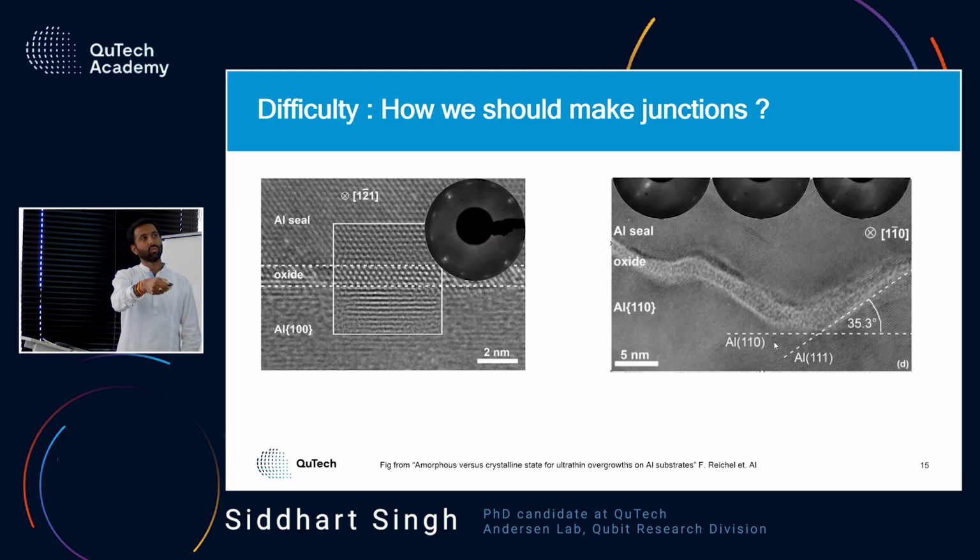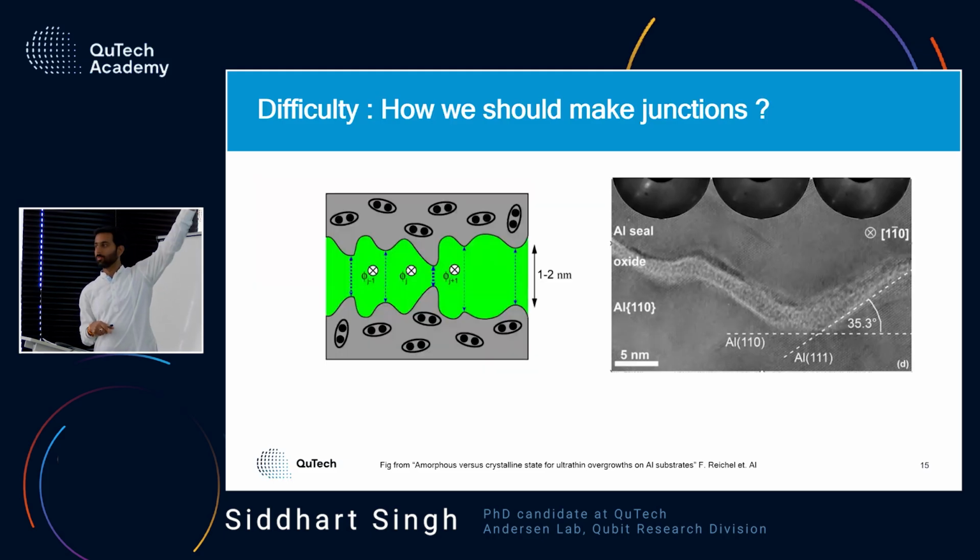And the thickness of the oxide is also varying across the whole thing. What this does is, when you have a superconducting phase in your material, your Cooper pairs will tunnel through the minimum of the barrier, because that is the point where your Cooper pairs tunnel through. And this becomes a problem when you think about putting two of these junctions next to each other. You cannot have a very consistent reproducibility over first the junctions and then across chips. So those are some difficulties which we face.